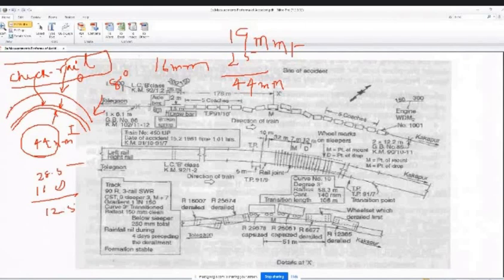So actually here, how the derailment will take place means, say whenever the 8 degree curve is there, normally loco pilots are advised to go at a normal speed. That means a very restricted speed. What is the restricted speed? For example, say 30 kilometers per hour they have to go. So why is 30 designed? Because here the forces that are there, the radial forces, if 30 kmph is not maintained, if it is maintained at some 90 kmph, what will happen? The radial forces will predominate and will go like this. Derailment will take place like this, and it may lead to bigger accidents.